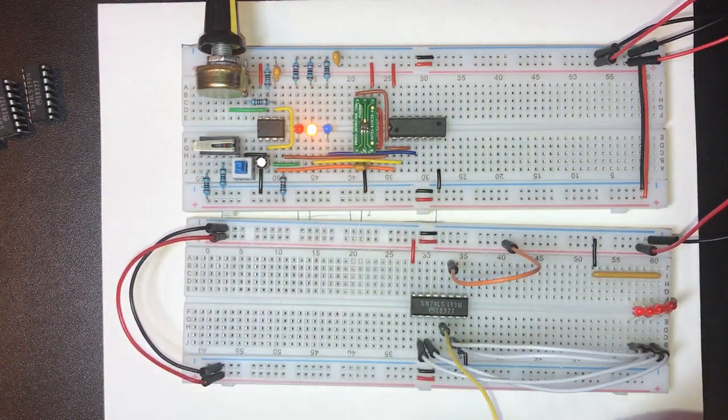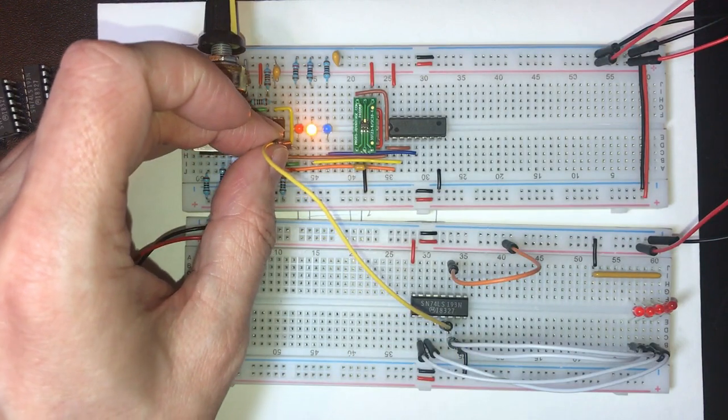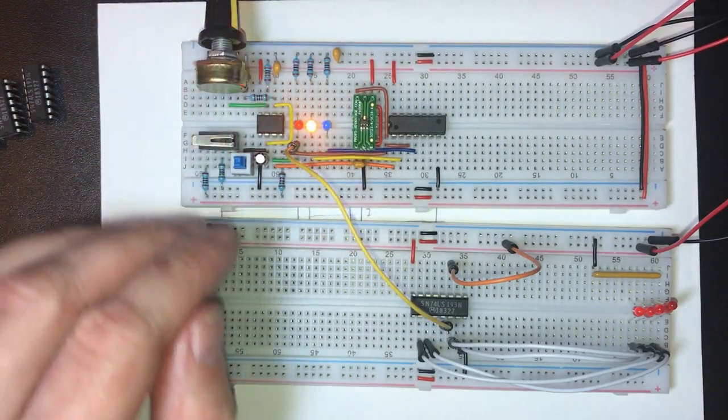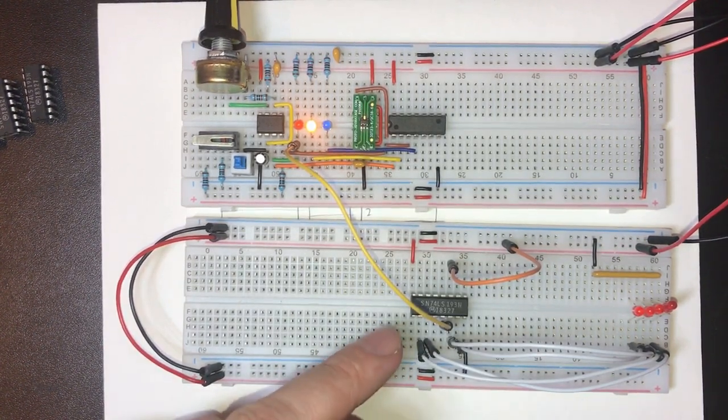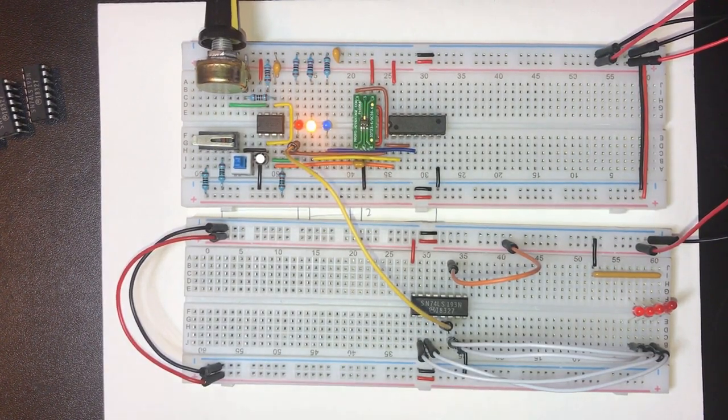Obviously we wouldn't necessarily use the clock as an input to one of these. Okay, why is that not doing anything? Ah, of course. The master reset is active high, but as a TTL chip, the chip has internal pull-up resistors, so any pin that we don't connect is going to naturally float high up towards the 5-volt rail. So this chip is constantly being reset at the moment.